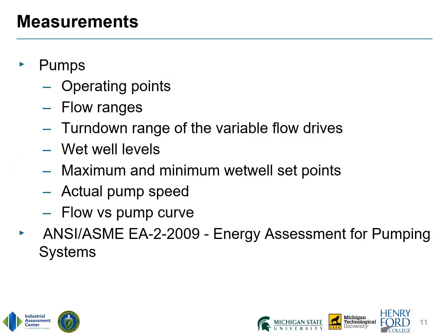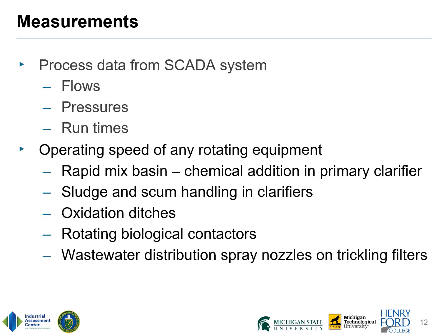As previously mentioned, pumps are large energy consumers for wastewater utilities and often provide room for improvement. Make sure to also record the pump operating points, flow ranges, turn down range of the variable flow drives, wet well levels, and the maximum and minimum wet well set point possible. Check the actual pump speed and flow versus the pump curve.